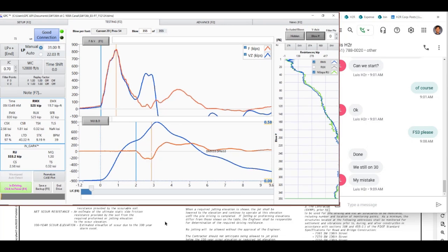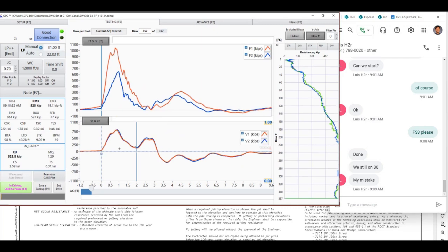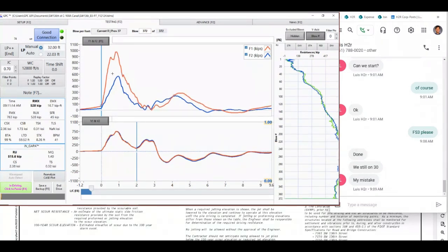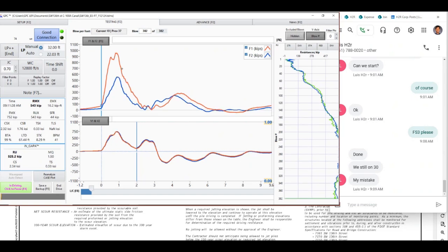So let's view this. The accelerometers are perfect. Velocity is the integration of the accelerometers, and the record is perfect. The two acceleration and velocity records are almost the same, so it's perfect. There's some gap here, which indicates a little bit of bending forces. On side number 1, it's a little bit higher force than on side number 2, which is okay. We don't need to do anything.